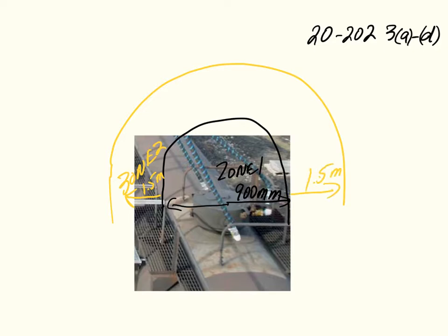Now, if we actually consider that these measurements are based on an open dome system. Open dome simply means that we vent the tanker itself just by opening it up. Now, the picture doesn't necessarily show that. You can see we have 3 pipes coming in there. And because I'm not sure of this tanker, one of those may be a vapor recovery system. But my hunch is that all 3 are actually transferring fluid. And therefore, this is considered an open dome where they'd have a vent just kind of somewhere on the tank that vents that gas-air mixture, and therefore these measurements would apply.